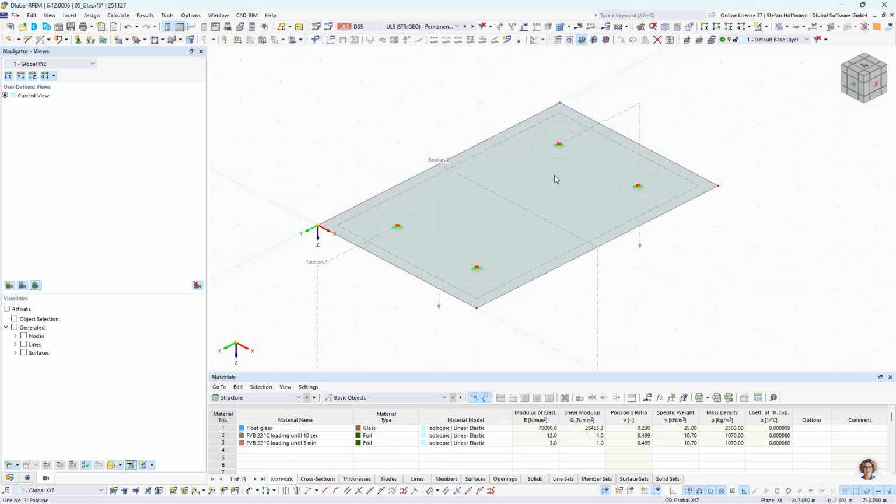What I would like to add is the function over here to add something to the selection or create a new selection. Usually you can mark the surface, hit the Control key, and add more objects into the selection. But if you are tired and do not want to do this, you can check this button and click objects once after each other. But this may cause trouble if you do not remember you activated it, because then a left click will not undo the selection. You have to click Escape.